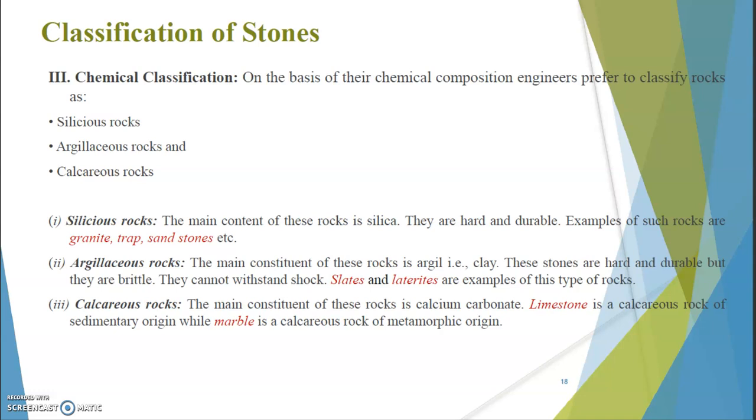Argillaceous: argil means clay, right? These stones are hard and durable, but they are brittle. Yes, the clay based rocks may look hard and durable, but they are brittle in nature. Brittle means without having plasticity during failure, it will fail immediately.